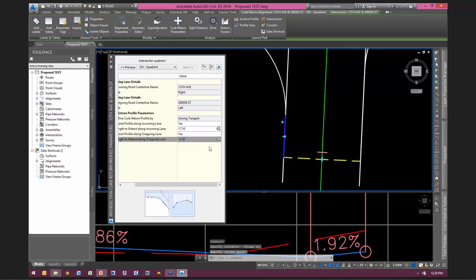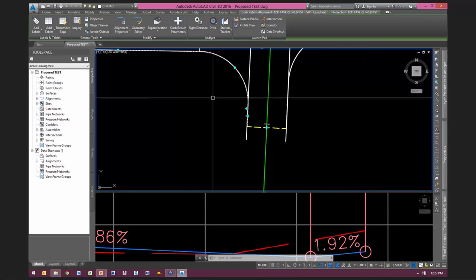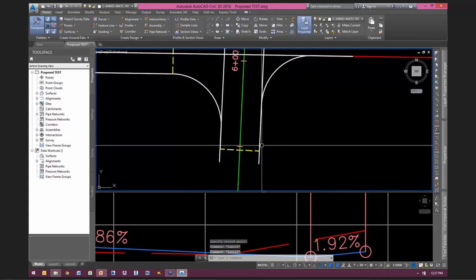And when I do that, it's going to put in that default value, or that value of 12.5, and it will also have adjusted that length right there. So why do we care about that? It's these exact endpoints right here, the length along here, that dictates how far that corridor is going to build. So we can use these to dictate where we tie in to the existing road, or where we leave off our project for future development. And that's the case that I proposed in this one here. So that's what curb return profiles are about. It's controlling where that project will end and start.